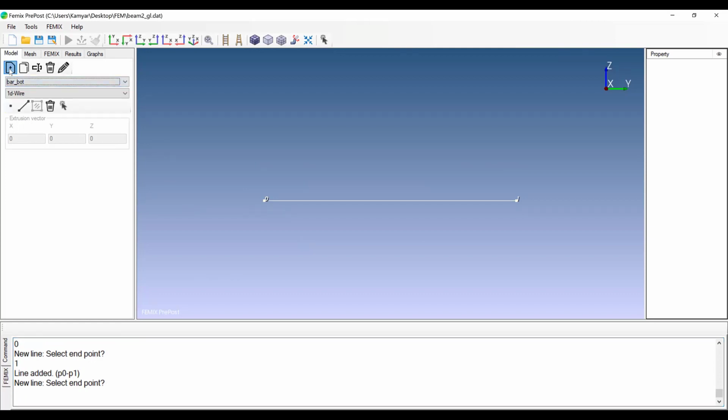And also we have stirrups. They are wire elements. I draw the coordinates. It's 0, minus 20 and 0. It's 0, minus 20 and 400. And also I can just click on edit on Notepad and just input from, if we have another model, we can just copy from an existing model. I had these in another model. I modeled it before. I just open the file.